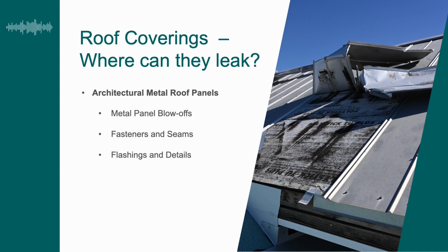I want to show you an example in this picture of why it's critical to select the right products for underneath certain applications. When picking a metal product for your roof surface system, you want a system underneath, your waterproofing, that works friendly with the metal, where the metal will not be stuck to the subsequent application. You can see here a little bit of asphalt bled through on this product, and it helped hold the tile in place. So with expansion and contraction between your hot and warm climates, it decreased the product's survival rate.